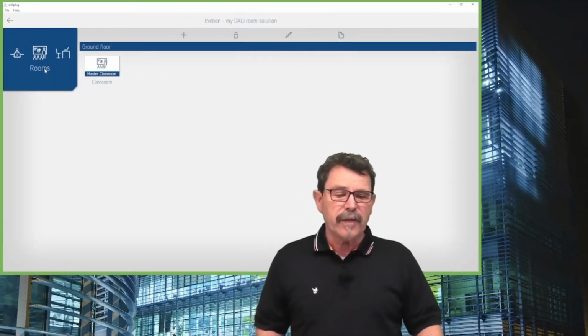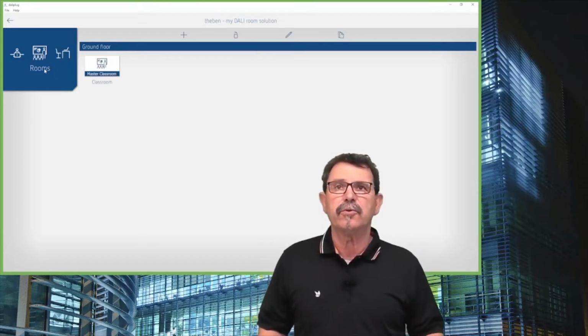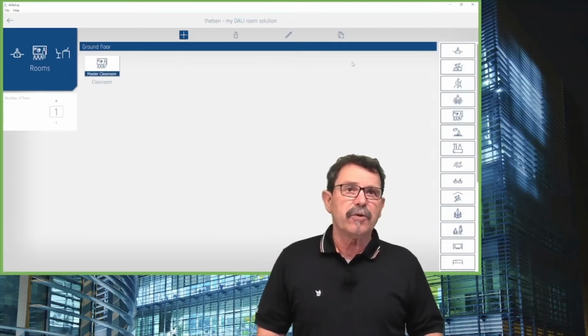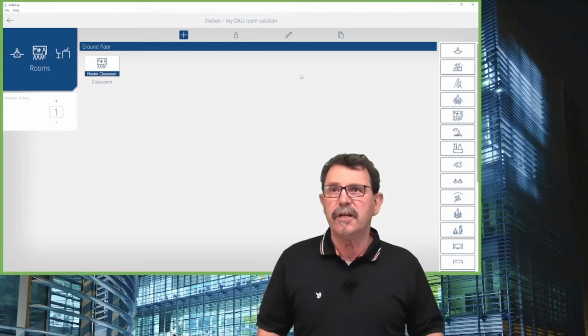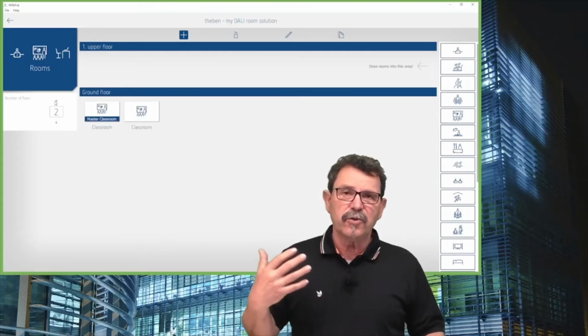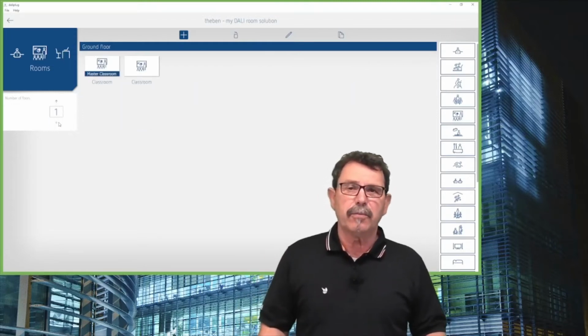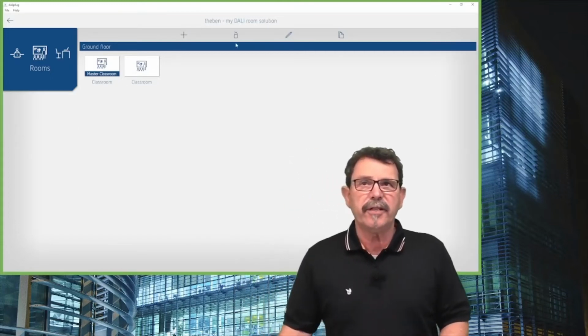So we have a new project. We intend to do a setup for a specific room. Just to make you acquainted, you see just one room, only for our exercise. If you want more rooms, click on the plus and import a few other rooms. If you intend to set up more than one floor, you can click here and add supplementary floors. With a click on the plus, you deactivate if you want to rename.